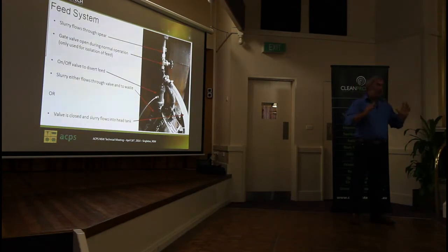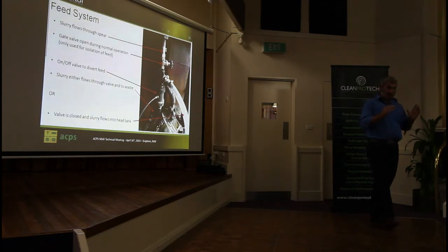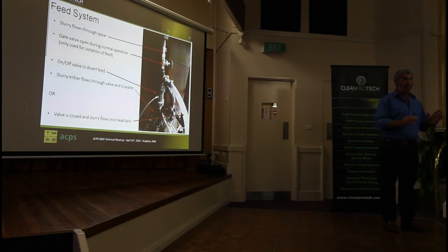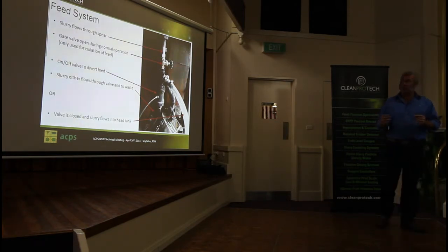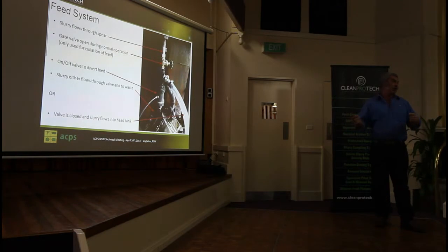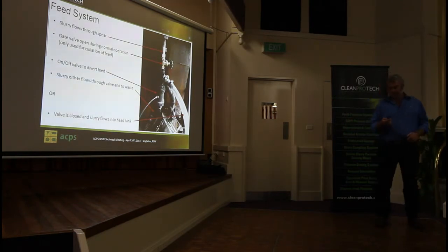We found that there was very little difference with the one piping setup with the position of the spear, but of course there was a huge variation over time. That's the big thing. Taking a good sample, the variation in time was far more than the variation in position. So if you were taking a sample to send to a lab, that's a very important thing. Because we're measuring it online, the variation with time is covered. Okay?